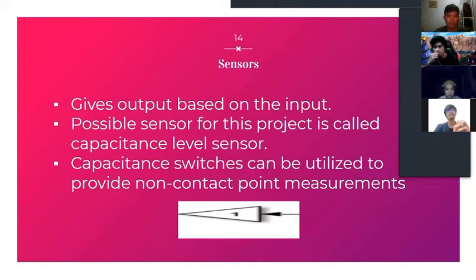The sensor is suitable if the wall of the tank is made from metal, which uses a single bar or insulated rod as one capacitor plate and the wall of the tank as the other. This type of capacitance sensor has already been used in aircraft fuel quantity indicators, which suggests that it is suitable to be applied for this system.